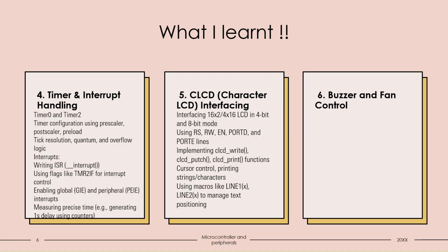At last, we have also used buzzer and fan control. In output peripherals, control via PORTC, RC1 equals buzzer and RC2 equals fan. Logic to turn the fan and buzzer on and off based on conditions or states.